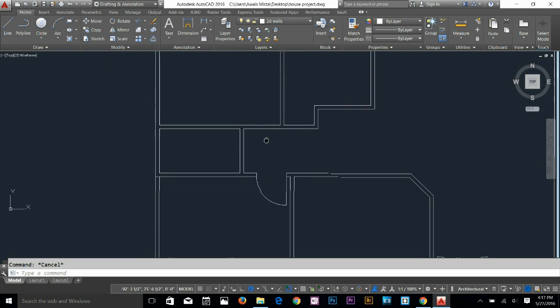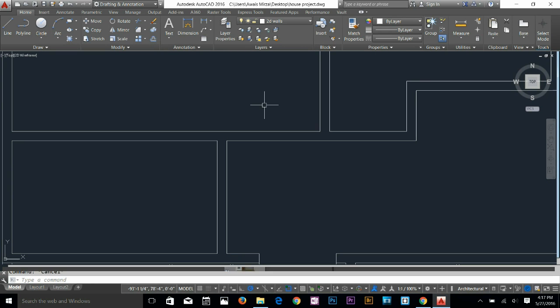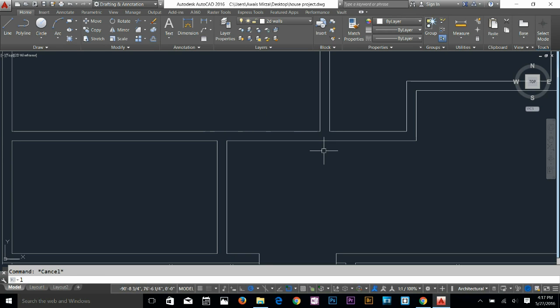So what I can do now is, let's check the distance of this door. Can we make a door there? So I'll make the same door there, 4.5". About, let's say 3 feet. Yep, I can do that. And then I'm going to select this vertex, drop it down, select that vertex, drop it down, TR for trim command, select these lines, get rid of this line.